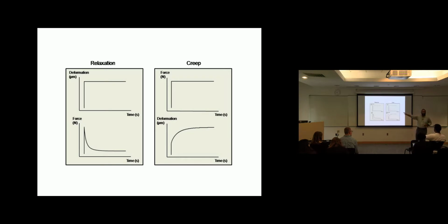That actually has to do with plasticity. I'll come back to it later. So here the assumption is that the number of crosslinks is fixed. You have a certain number of crosslinks. You're not really deforming the heck out of them. It's only a small deformation. Once you do larger deformation, I'll come to that later. So the number of crosslinks is fixed, and that works in many situations.